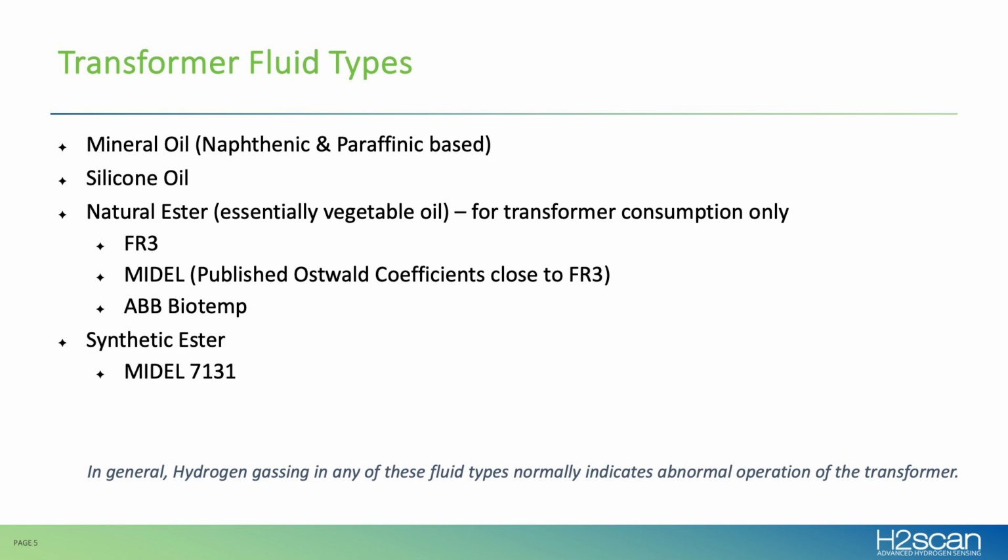So it became, I think there were probably other reasons, but today you still see some silicone transformers around, but not many. Most of the industry is really focused on the ester fluids today. And I call ester a fluid, which is why we're talking about transformer fluid types, because the ester fluids are not considered oil.